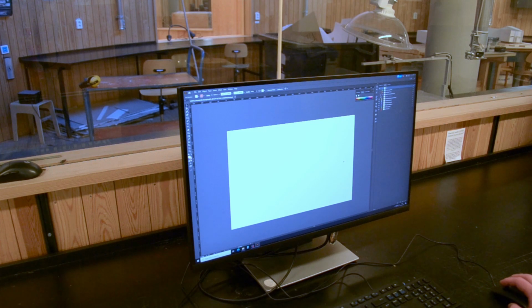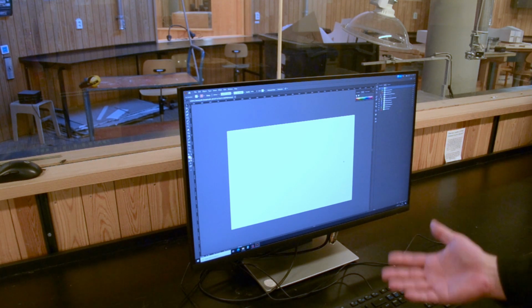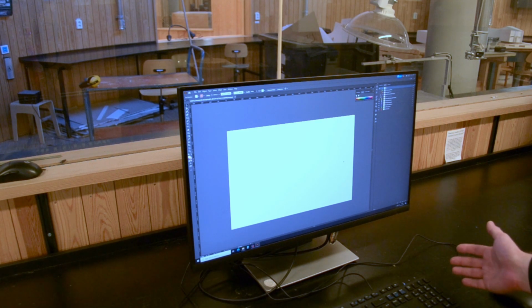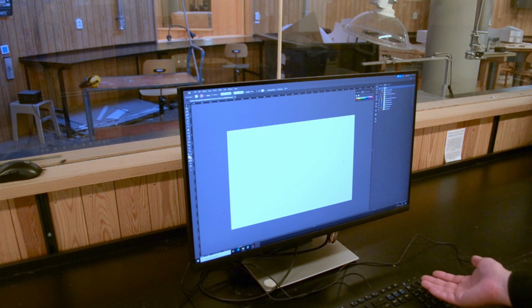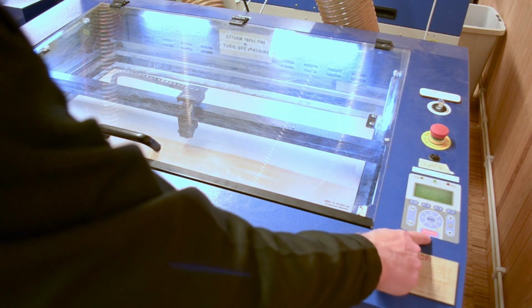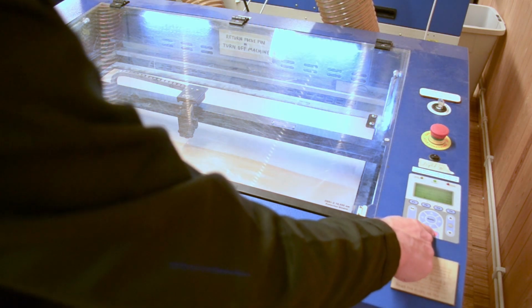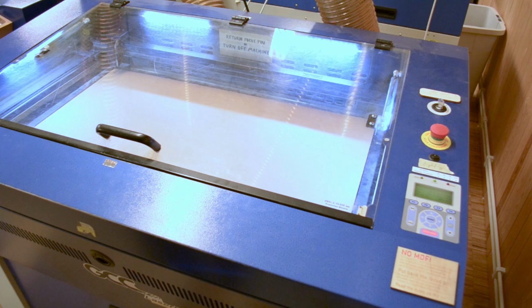If Illustrator freezes or does not consistently want to send the illustration to the printer, then what usually works is turning off the laser cutter, signing out of your account, switching on the laser cutter and logging in again. Verify that the index number has been updated and that the file name is correct, and then press the red Start button to start the job.